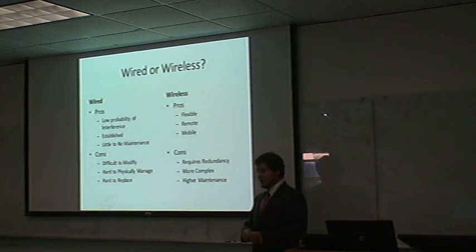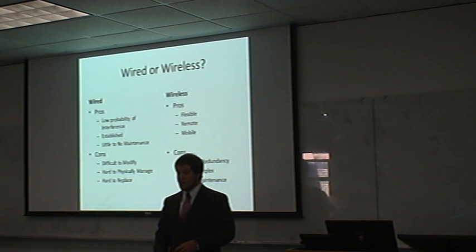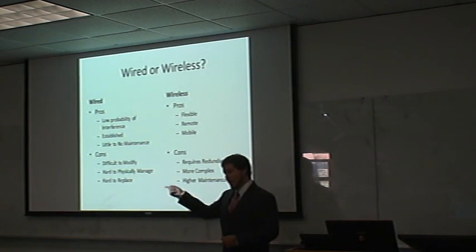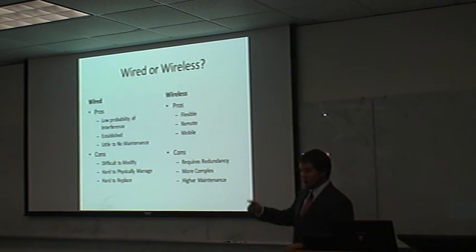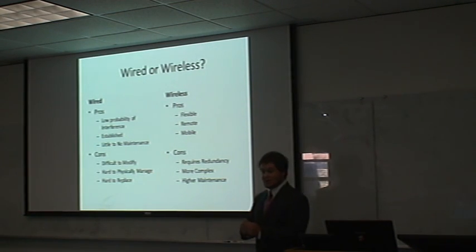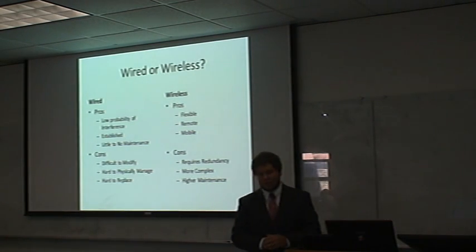Now, if we went to the other end of the spectrum and wired everything, 100% wired, and we had 200 sensors in here and had to run them all the way back to the main campus, we'd have 200 wires going all the way back, and somebody would have to sit there and splice all those wires. So there's a real big trade-off there between flexibility and power.